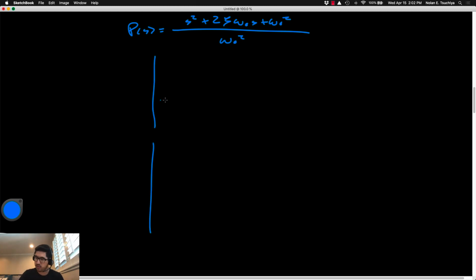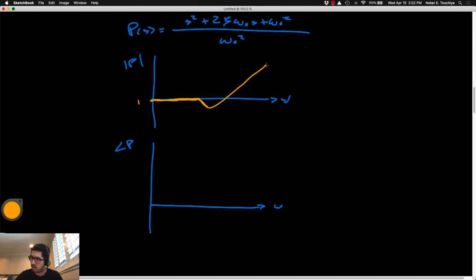And in this case, just as you would expect, you would see basically the inverse of what we saw for the previous second order system. You would see basically 1 up until you approach the undamped natural frequency, omega naught, and then you may see what's called an anti-resonant peak where it dips before increasing and magnifying at a rate of 2 decades per decade. So this is referred to as an anti-resonant peak. Okay, and that would occur at the resonant frequency.